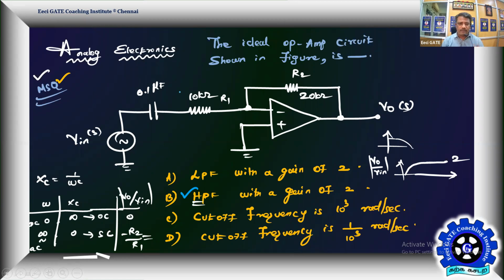If you want me to prove it straight away, I can say this is the high pass one responsible for the frequency selection. So 1 by R1C will be the cutoff frequency. R1 is given as 10K, C is given with exact values. Probably this value exactly matches the given GATE problem as well, in GATE 22. Yes, the R and C product will be R1C, so 0.1 into 10 will be 1, and micro and kilo will become milli.